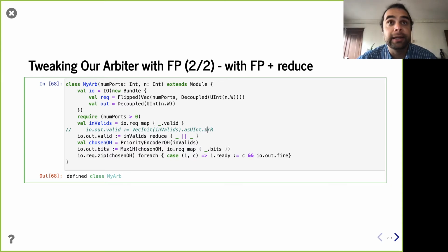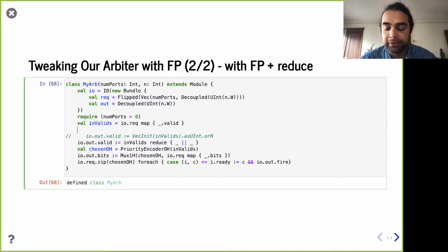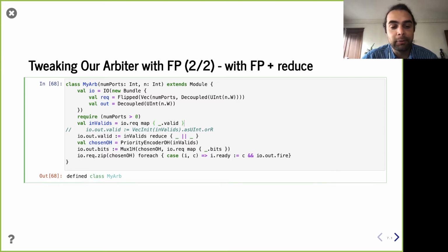These are just referred to as reductions. Interestingly, they come up just enough in hardware design that people actually put them in languages. In Verilog, you can just use a single vertical bar in front of a variable to do an OR reduction. It's weird to have an OR bar without something on the left, but it actually works as an OR reduction. It comes up in hardware design where a lot of times you want to know, is any one of these bits true, right?